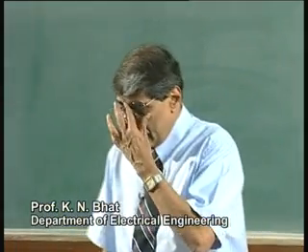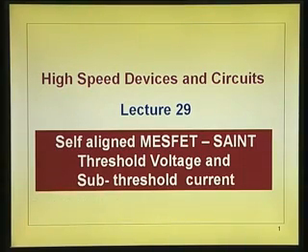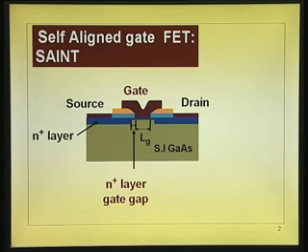So, today we continue to discuss the MESFET with particular reference to threshold voltage and subthreshold current. In fact, we have discussed the effect of the channel length and also the effect of the spacing between the n plus layer and the gate, that gap.